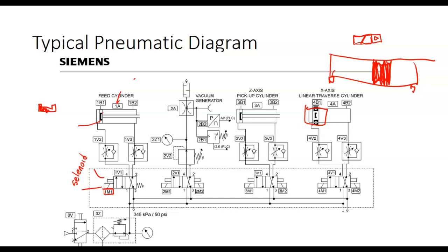No, you have to send it back with fluid power. So we've got two ports. It doesn't automatically come back. We put pressure there, it causes it to move this way. We vent, we exhaust this side, or we come over, put pressure on that, and exhaust that side. So it's just like a cylinder, except it doesn't have a rod. And somehow, what we're trying to move with it latches onto that puck in the center. I've seen them with metal belts that come out and loop out, sealed up really good.